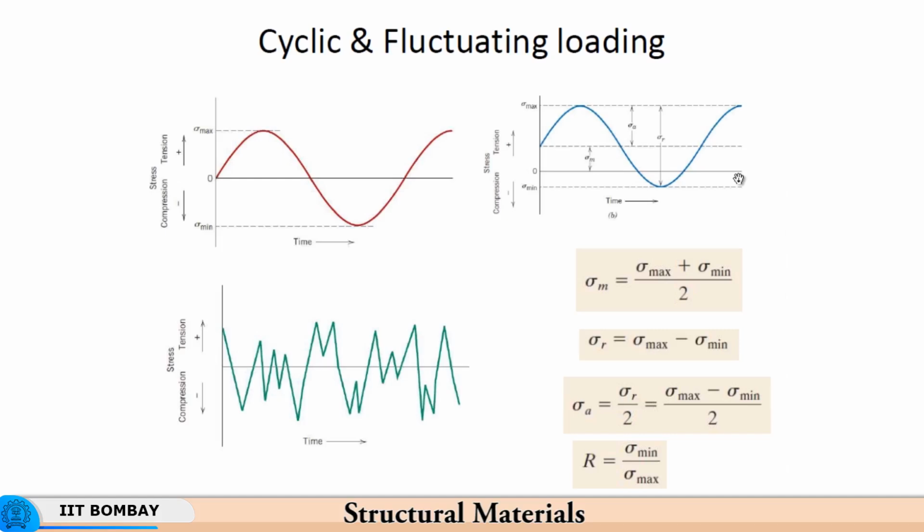So, let us say that this point rises right up to 0. Then the cycles are something like this, where it starts with 0, goes to a maximum, comes back to 0, again goes up, comes back to 0, again goes up. The maximum is at operating pressure, the minimum is at atmospheric pressure, and this continues over a number of cycles.